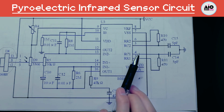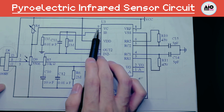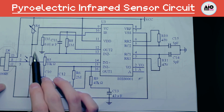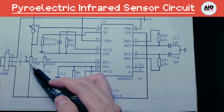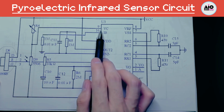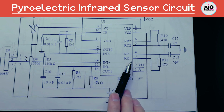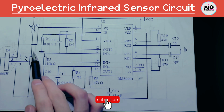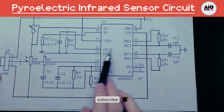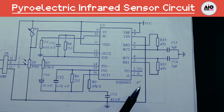Then the output of the second operational amplifier is internally connected to the bidirectional voltage converter. So after passing through the voltage converter, its signal will pass through the logic control part and the delay part. Pin 9 here is the enable terminal just now. A resistor is connected to this side and a photoresistor is connected below. When the light intensity is strong enough during the day, the resistance of the photoresistor is relatively low. So at this time, pin 9 is at a low level, and the circuit behind it does not work.